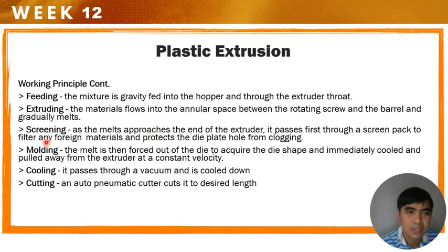Next is screening. As the melt approaches the end of the extruder, it passes first through a screen pack to filter any foreign materials and protect the die plate from clogging. So here there is the addition of a screen.